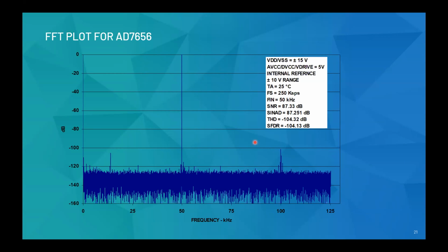In order to do this analysis, we would have an evaluation board with an FFT analyzer algorithm. We would feed a very precise audio input or a signal input in order to make sure that we have very low noise in the signal itself, and then give these evaluation plots to the customers for evaluation.